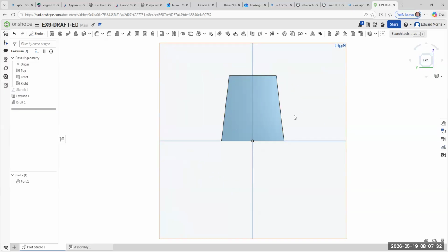Now, if you were to rotate this upside down or rotate this 180, for example, you see the tapered set. If you were pulling this out of a mold, it's going to release better. Also with forgings, when you forge something, or even when they're forming plastics, you put a cup. You've seen a cup you drank out of? Look at a cup. Usually the cup has a slight what? Draft angle to it. Why? So it will release from the mold easy or from the die.